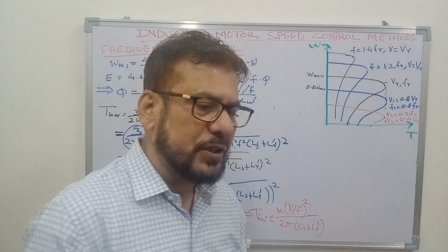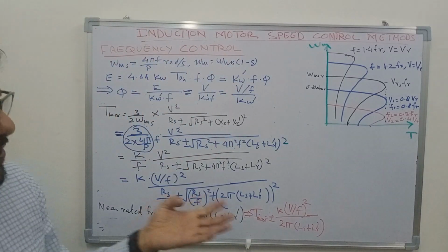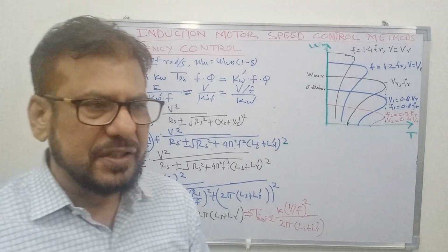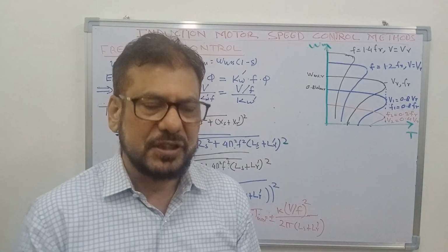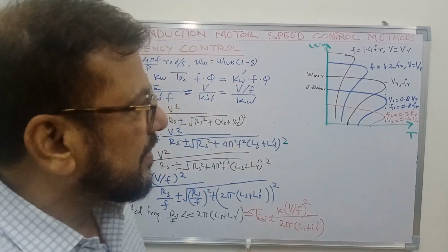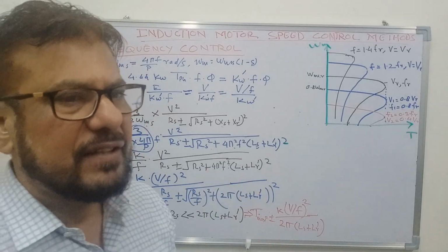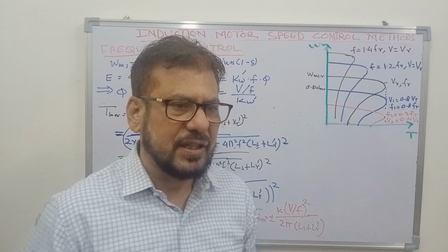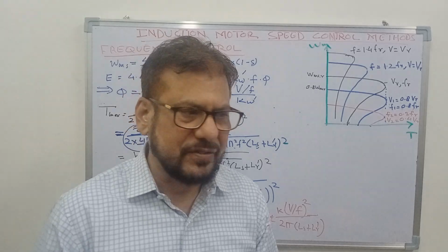So this is a very good method and the most preferred method. But here, as you see, it is a complex method. You have to simultaneously change frequency as well as voltage. So that makes the system more complex.